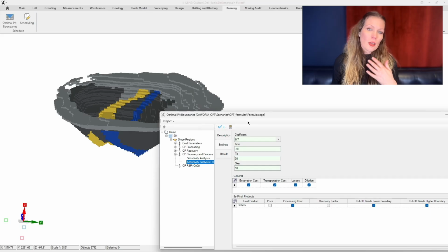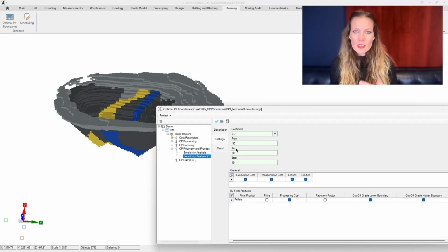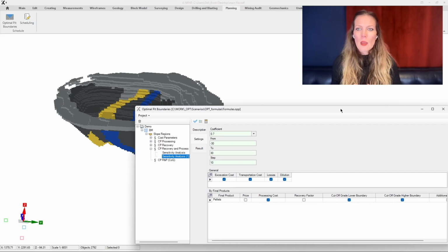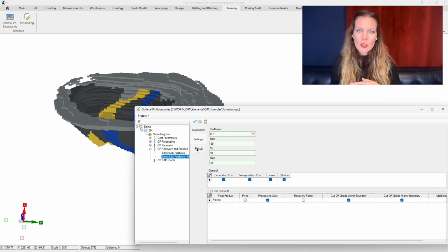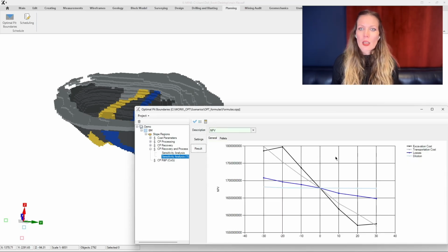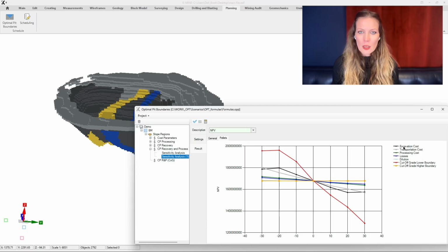However, if an underground phase is planned, some of the deeper low-grade ore can still be reserved for later. Instead of pushing the pit deeper and spending more on stripping, mining can stop earlier and shift underground. The same material can then be mined more selectively and efficiently. This makes it critical to define both the final pit shell and the underground cutoff grade together.